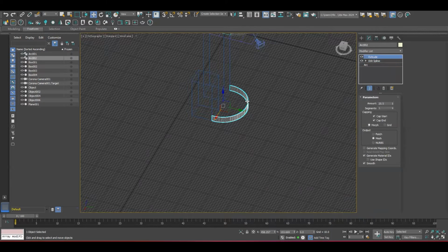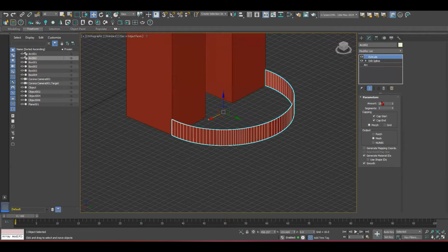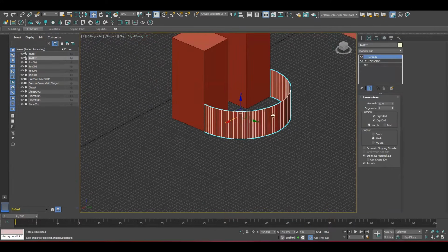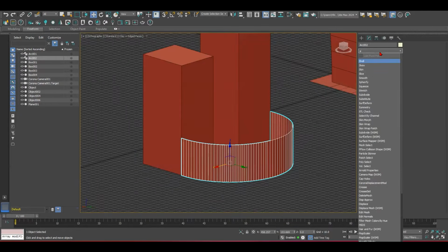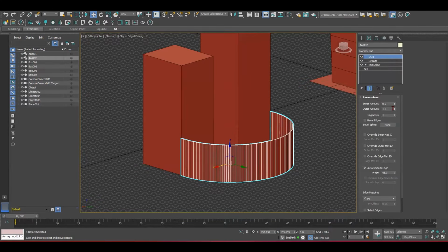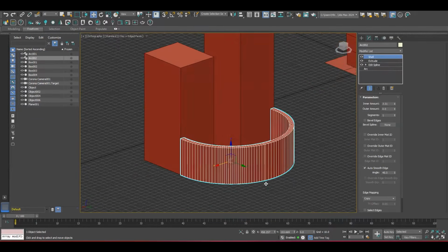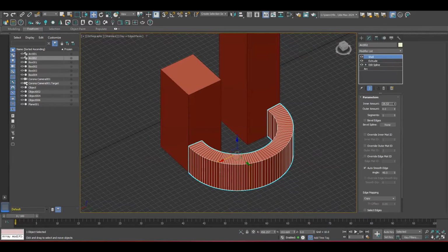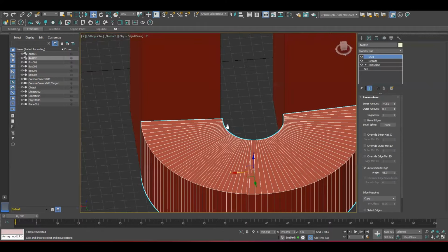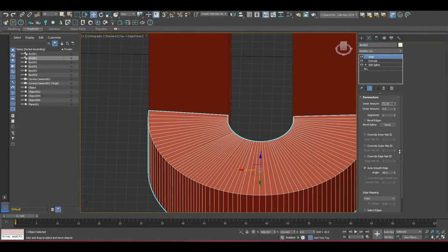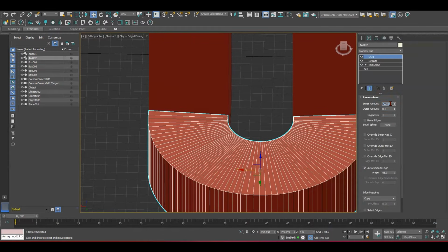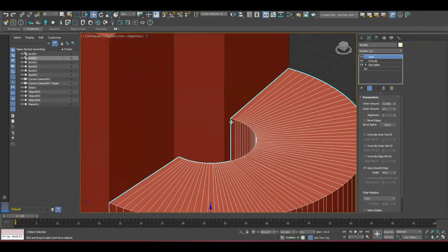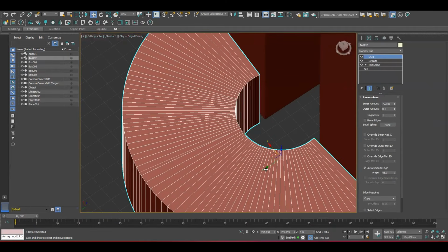Once I do the extrusion, and that's going to be this height, for example, then I can do shell, give it more interior thickness, then I can just edit on it once I start the design process. So to be accurate, I can get just the width of this, and I add this here. So be almost the same.